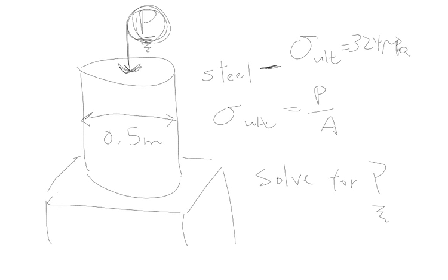There were no defects in it. It was made correctly. It was heat treated correctly, right? But what if someone had made a mistake? And this particular piece of steel that you used is weaker than what the specifications say. You would be in trouble if the customer actually tried to load this part right up to that breaking point, right? So out in the real world, we would never simply rely on that ultimate value, okay?